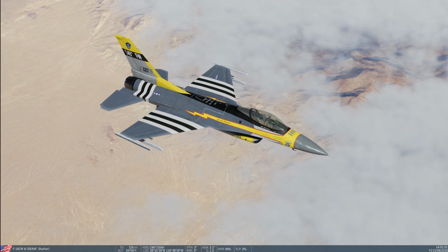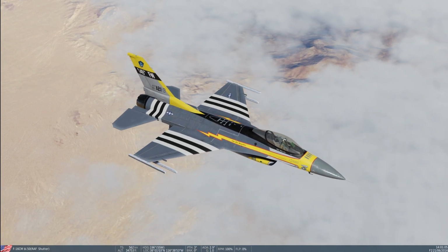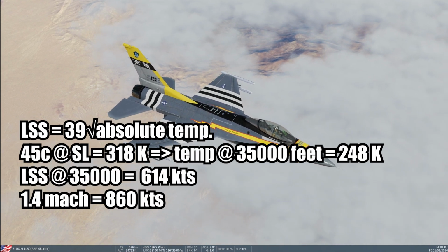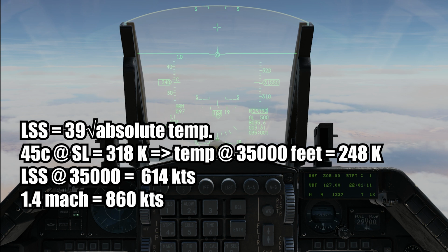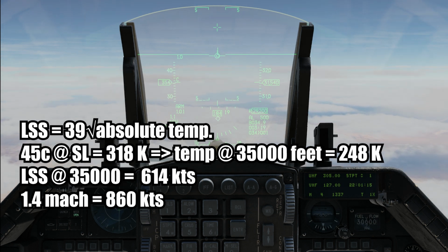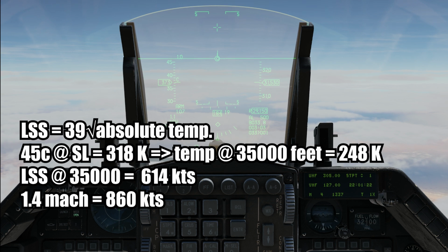At last, we have arrived at the Mach number. There are two numbers of interest to us here, true airspeed and the local speed of sound. LSS, as it's abbreviated, is dependent on the air temperature. That means that as you climb higher, the speed of sound will be lower. This will also be compounded by the temperature at sea level. A lower temperature will result in the same Mach number at a lower TAS.